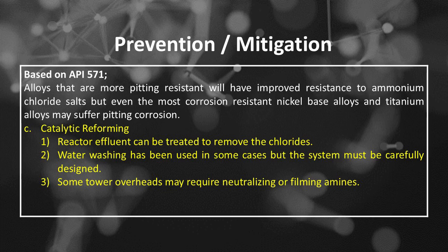Number 1: reactor effluent can be treated to remove the chlorides. Number 2: water washing has been used in some cases but the system must be carefully designed. Number 3: some tower overheads may require neutralizing or filming amines.